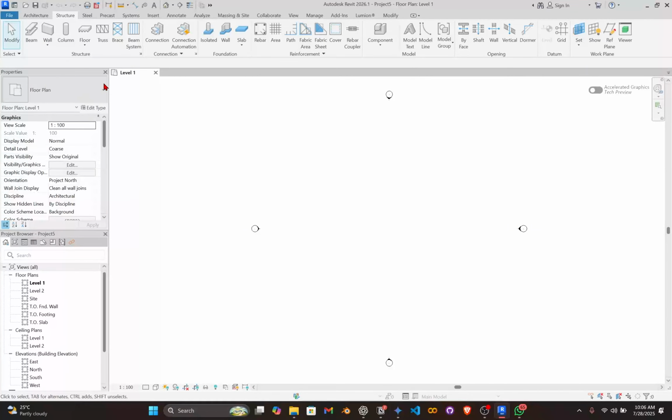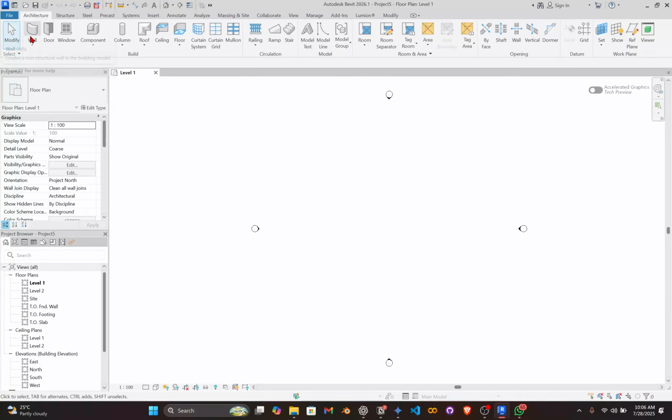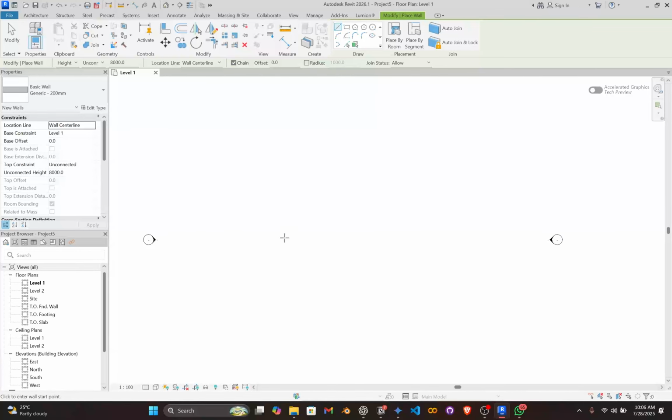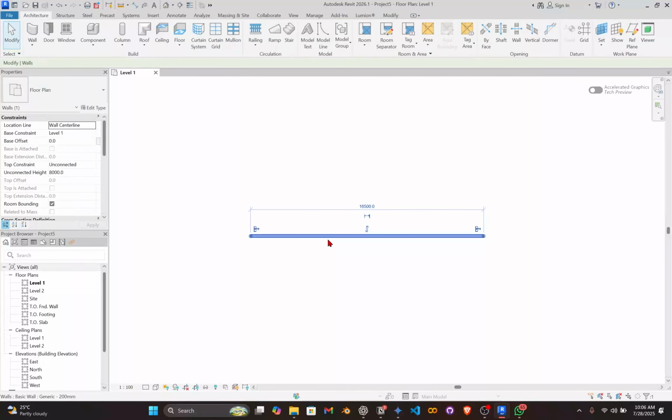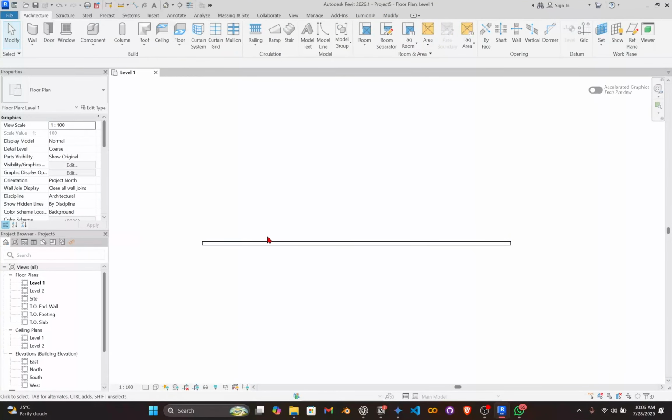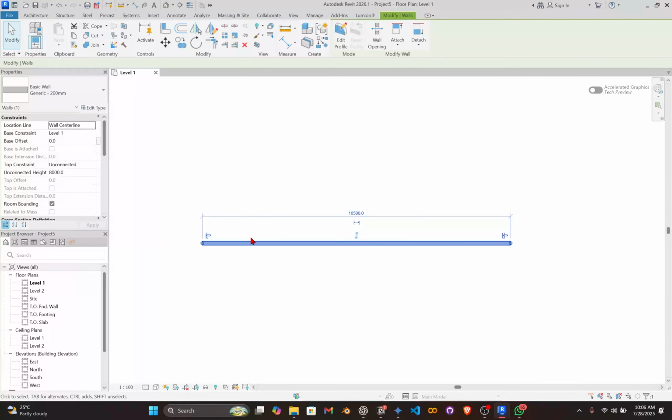And now, when we look at this side, we have what we call the properties tab. So to demonstrate what the properties tab does, I'll quickly draw an architectural wall. So this is my architectural wall. Now, to be able to make use of the properties tab, you have to make sure you are selecting a BIM object, right?